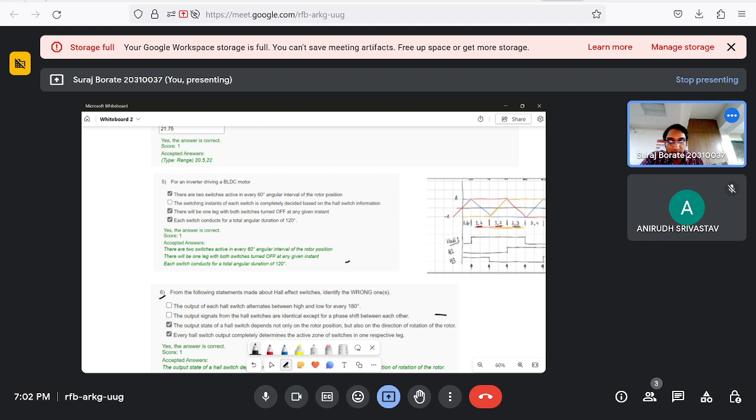So the field generated in BLDC motor is rotating along with the rotor. Yes, so that is a correct answer. Why? Because the magnet is on the rotor itself. So it creates the field beneath. So this is the correct answer. Armature conductors are powered without the need of brushes. That is what we discussed, obvious. So let's move on to the next question.